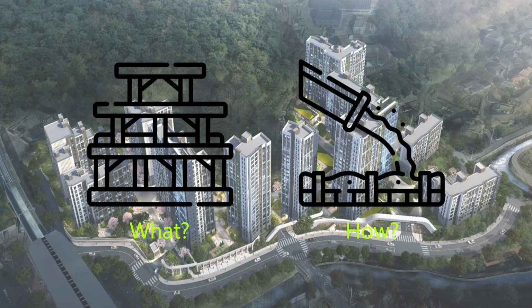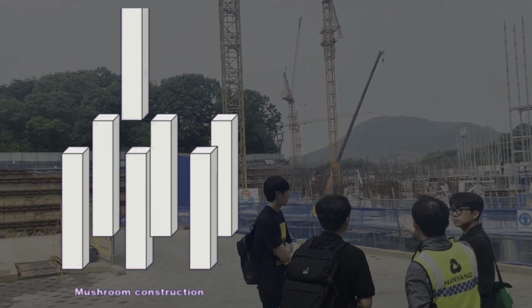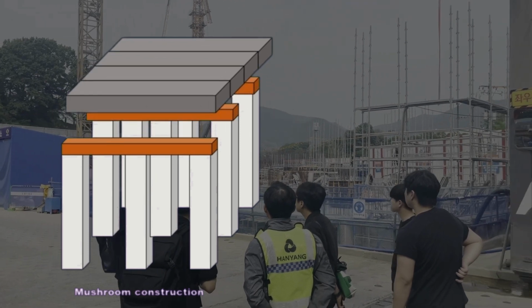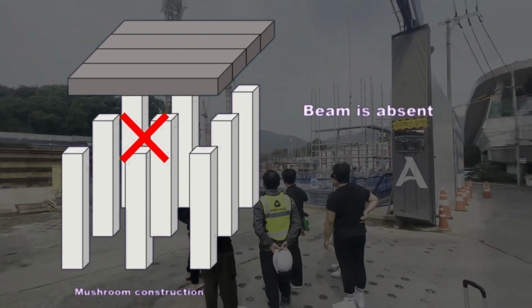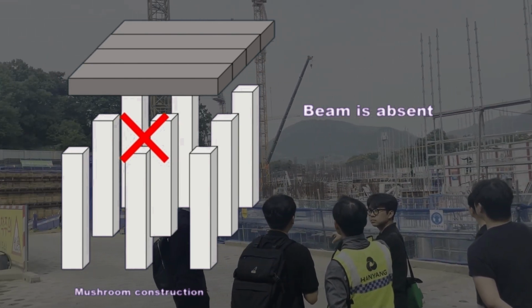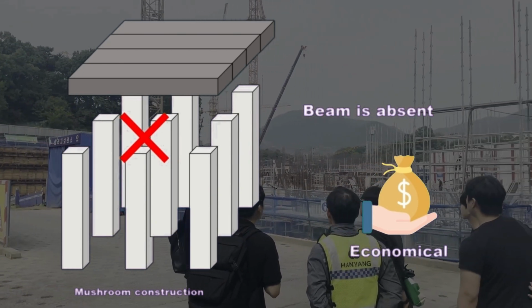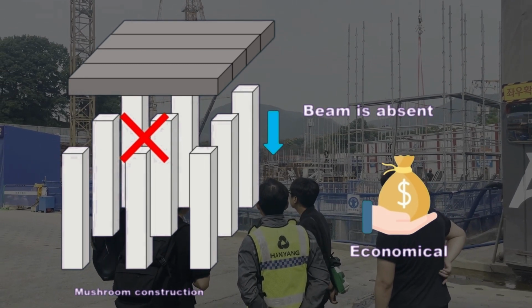So, what kind of structure and construction method is used for the underground floor at our site, Hanyang-Sujain River Pine? Mushroom construction is a form of reinforced concrete structure in which the horizontal structural member supporting the load, the beam, is absent and the slab is directly connected to the vertical member, the column, which supports the load of the building. This structure has the advantage of being more economical than rigid frame structures in various aspects such as excavation, due to its lower floor-to-floor height since there is no beam between the column and slab.